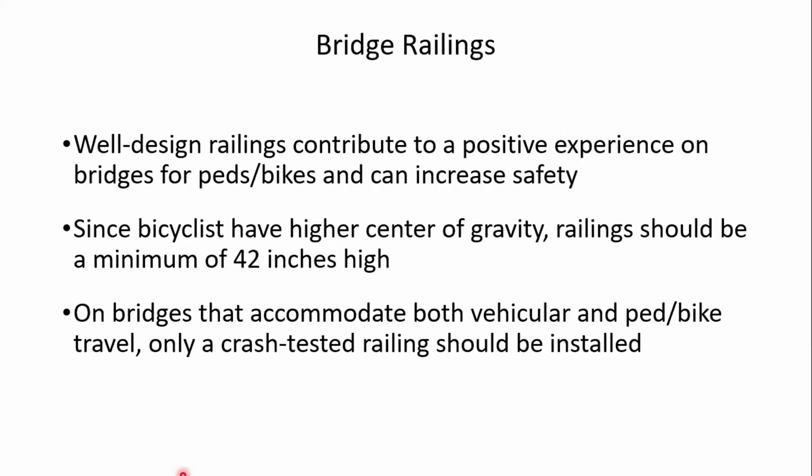Bridge railings, important for safety, of course. And keep in mind that bicyclists have a higher center of gravity, so the railings should be a minimum of 42 inches high. And if we have bridges that accommodate vehicular, pedestrian, and bike travel, you need a crash-tested railing.